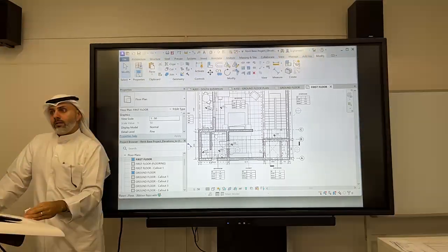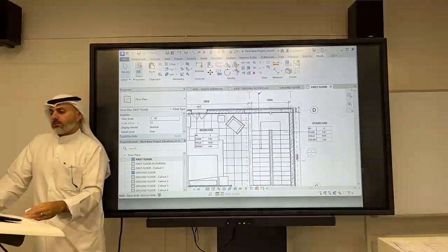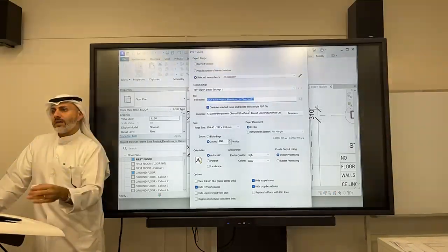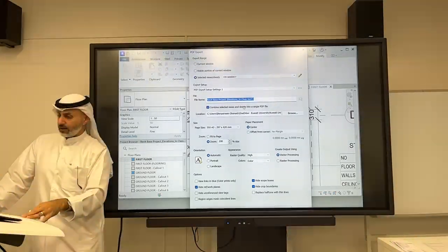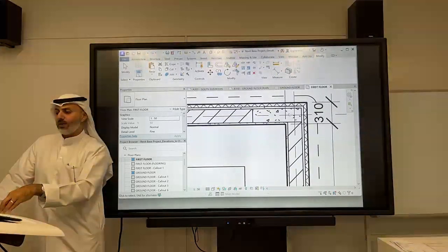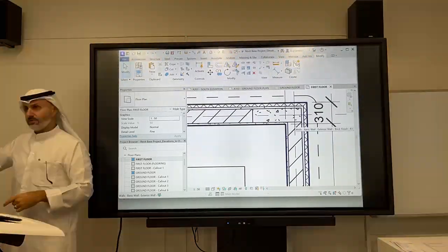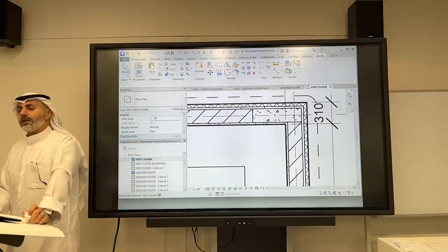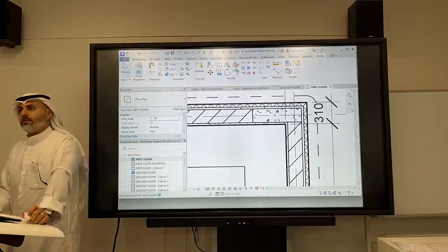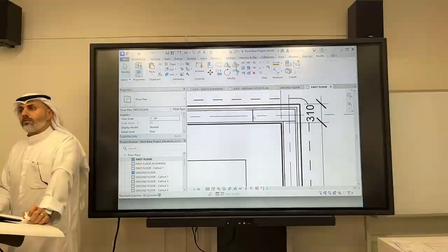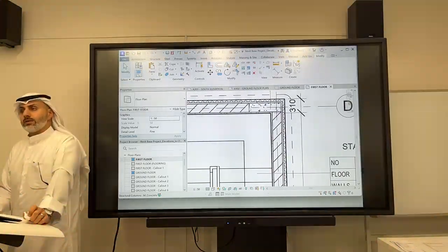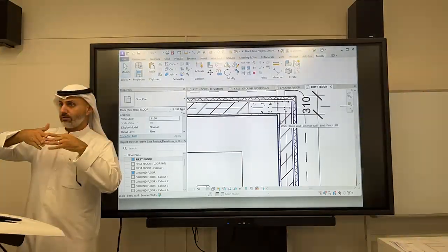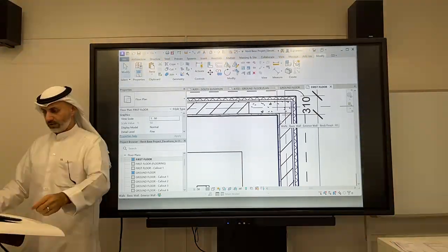So how do I know? You have to export. And the only way to find out is export to PDF. Export it and then look at the PDF and see if there's an overlap or not. This happened with me. Here it shows no overlap, but in the PDF I see the line showing. Because when I'm selecting them separately, when I select one wall, I select only the other side, more done together as one joint wall. It will still show them as separate elements, but you're telling Revit they should appear as joined. They're not going to actually be one element.